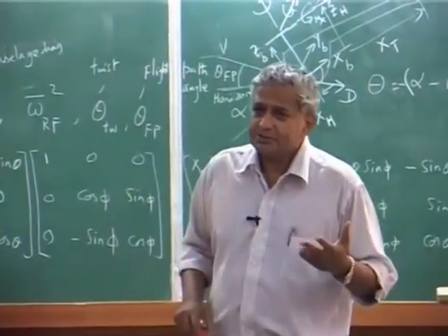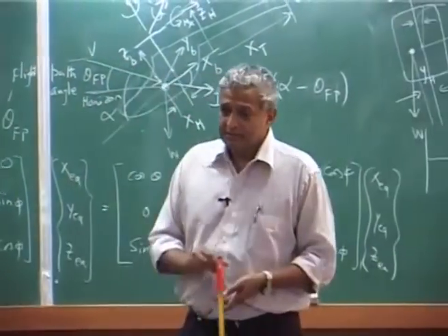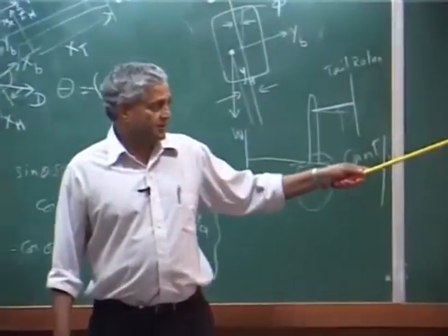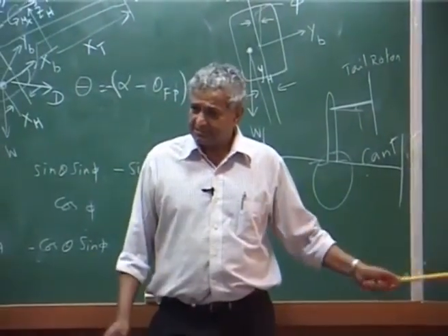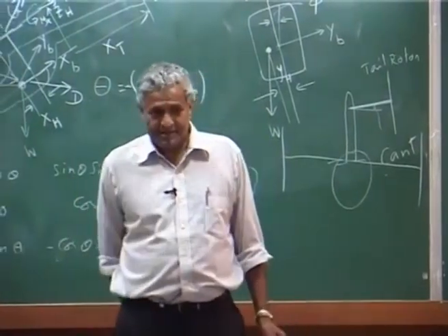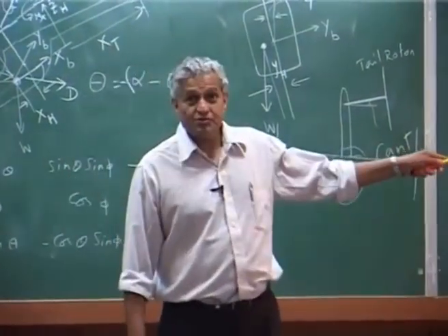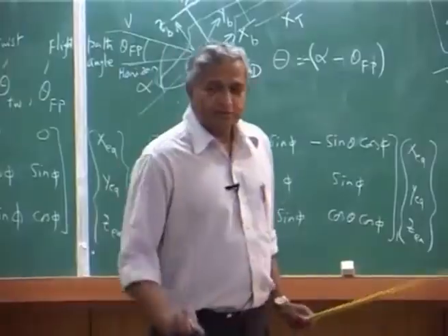So, what was the industry doing? Initially they do a lot of approximation, get a result first, after that they go further. That is why here, when I use flap only, you call it the flap term. And another thing is, in some of the research work, they do not take all the 6 equations, because I do not know the tail rotor, I am not interested.